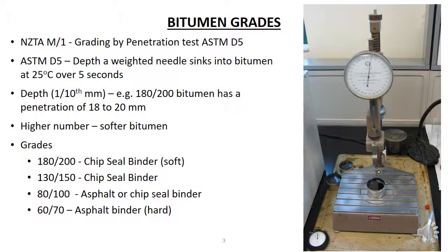Harder bitumens can be used for asphaltic concrete, as it does not need to flow as well as the sprayed bitumens for chip seal. The HE01 grade bitumen is usually used for asphaltic concrete, although grade 60-70 may also be used for higher traffic loadings. The harder bitumens are more rigid, but are also more prone to becoming hard and brittle in cold weather, which can result in cracking.